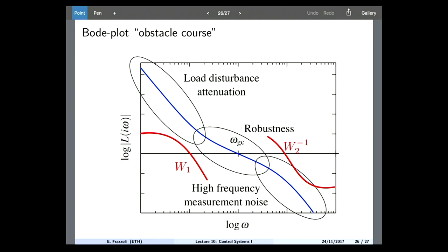Is there a sharp decrease or increase if we increase our frequency a little bit or decrease it a little bit? That is not necessarily bad, right? But you remember, at some point we said that the slope of the magnitude plot is actually related to the phase. In particular, if the slope is very steep, what happens to the phase? The phase is very negative. Okay, I see. So if the phase is too negative, then you are below minus 180, and then you are getting close to instability, okay?